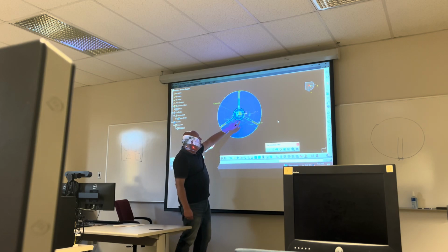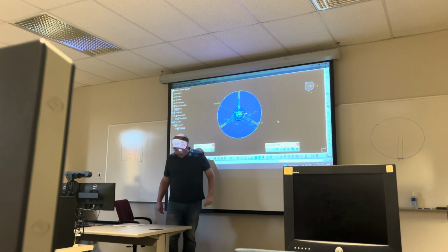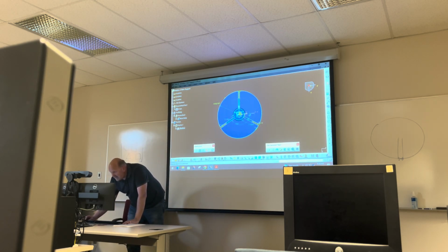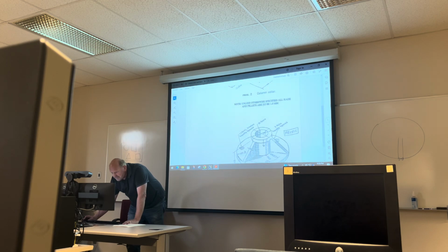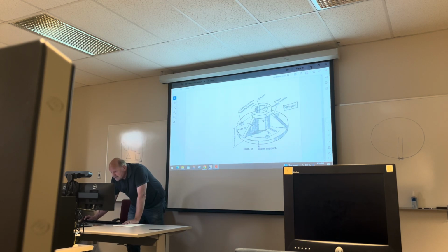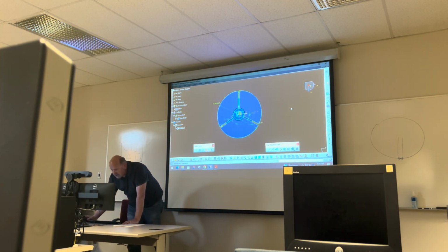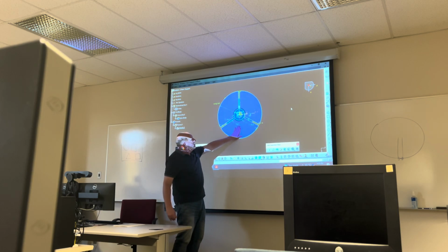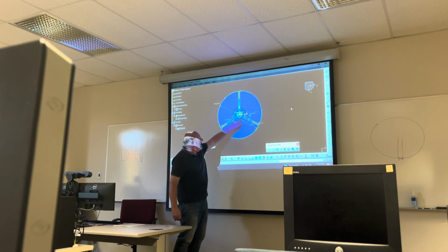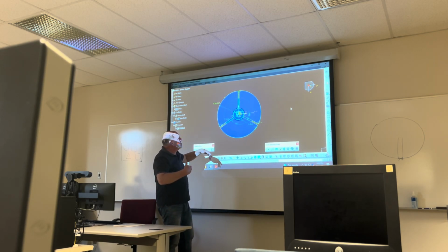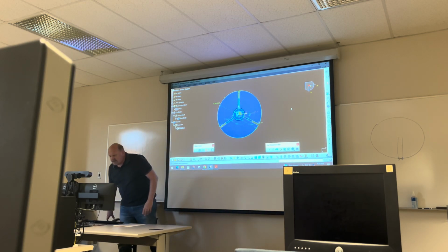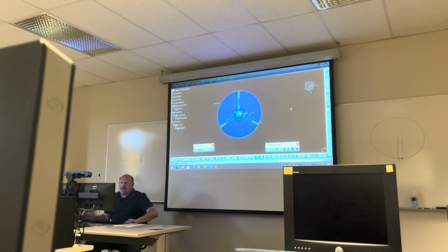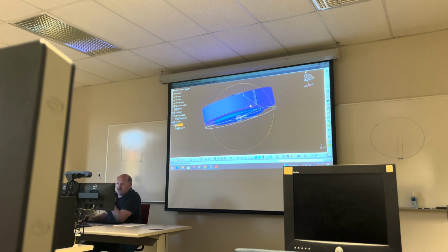And then, this is the undercut on the bottom of the part. I think it's 48, is it 48 in diameter? .44 in diameter. So there's the undercut on the part, because what you're looking at here is that you're building this pad or this pocket underneath that top edge, because when you subtract it out, it gives you the right value for that diameter. So once again, simple shapes give you what you need on the part, and let me show you, when I exit this, the way it has to be built. It's hard to see like this.